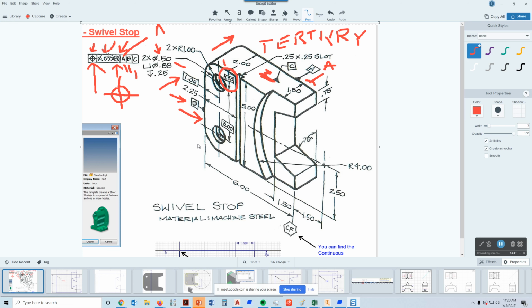All right. So we actually have a second hole on here, which is this hole right down there. And the center of that hole, this same GD&T note applies to this hole here. But this time, the location of that hole is also a basic dimension. It says it's 3 inches from the center of this hole, which was also located with a basic dimension right here. So you can see we actually have 3 dimensions right there that are basic dimensions.